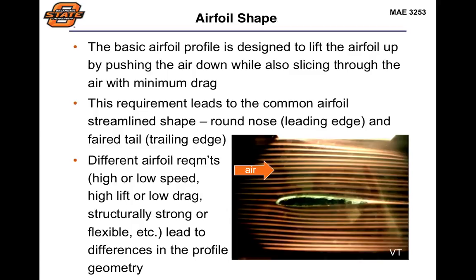Now, if we're just looking at the potential section of that, it's okay if we look at non-streamlined bodies, but when we throw on the viscous part, which is really that piece that we want to be able to utilize Xfoil and other panel methods for, that's when we can really only use it for streamlined shapes. It doesn't work so well when we start talking about separation behind bluff bodies or non-streamlined bodies or at high angles